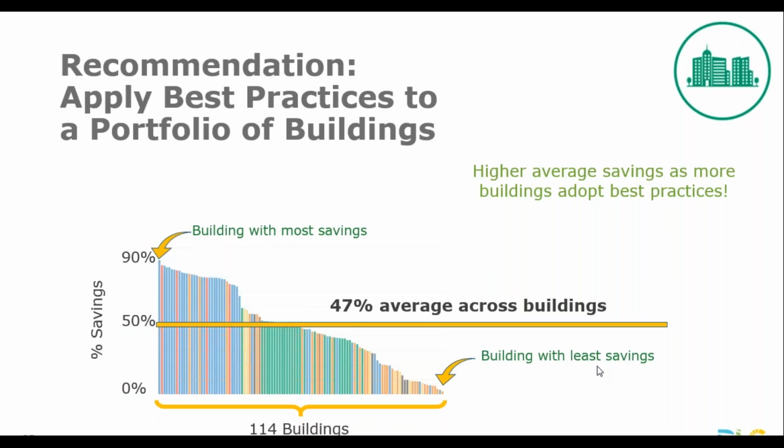Whether you're an energy efficiency program manager, a building owner, or anybody in the supply chain who's talking with building owners, you're more likely to see positive results from lighting controls if you can talk about a portfolio of buildings. And you can develop best practices to apply across all the buildings in that portfolio. For instance, you can make sure that all the systems are properly commissioned, so high-end trim, occupancy sensing, and daylight harvesting are all enabled where feasible.